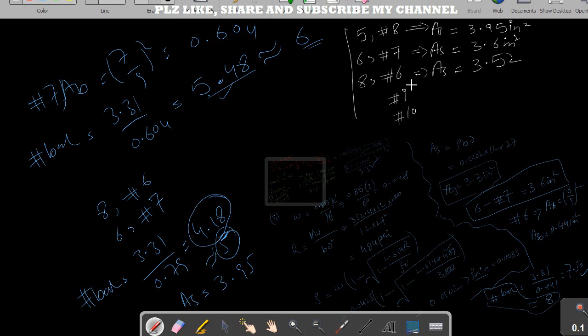For number 9 bar, the area of number 9 bar is 1 square inch. So this time I need 4 bars. 4 number 9 will give me an area of steel of 4 square inches. And number 10 bar area, 10 divided by 9 square, 1.23 square inches is the area of number 10 bar.